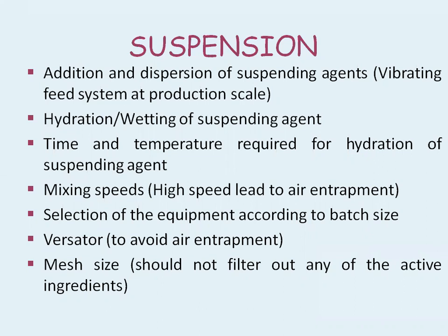If there is agglomeration of the powders, it is very difficult for us to mix it. So to break those agglomerates, we use a wetting agent or hydrating agent. It will remove the air which is in between the particles. In place of that air, this wetting agent or hydrating agent will enter, and in this way we will separate the particles.